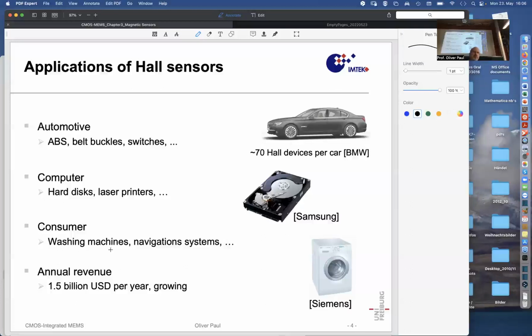Whereas a Hall sensor can be fully packaged, hermetically sealed by as many layers as you want. The magnetic field still goes through. If your sealing is not a magnetic shielding, then a magnet in a switch can be directed towards this Hall sensor to be detected as one position, or removed to be detectable as another position. The sensor is pervaded by different magnetic fields, which can be discriminated so that the machine knows what you intend to do and carries that out. And 20 years later, it still works.